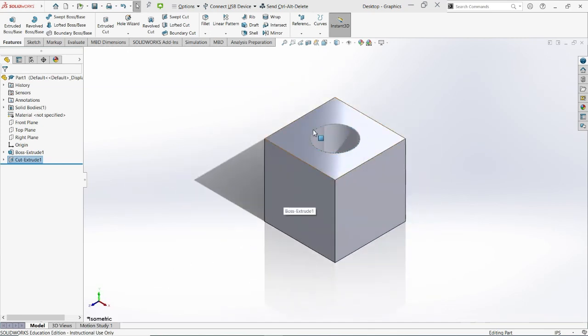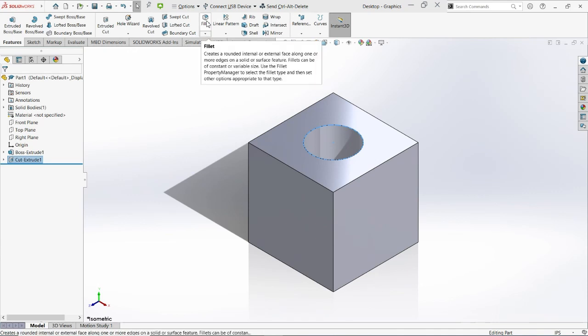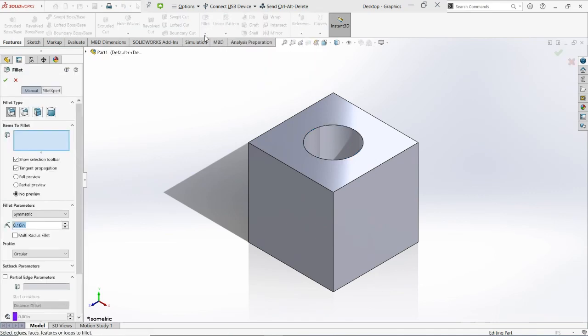So, as I was saying, what if you wanted to have a non-two-dimensional feature? Say you needed to round the corner off or something like that. Or rather, let's round off the corner of this circular profile here. In CAD, there are always going to be multiple ways to do something. In this case, we can either use a fillet, which is this feature here, or a revolution, and I'll go over both. But let's go over a fillet right now.